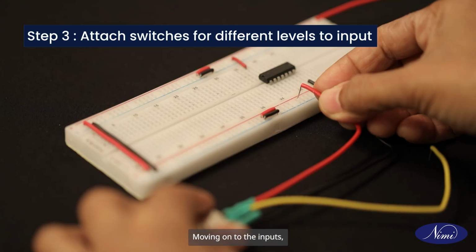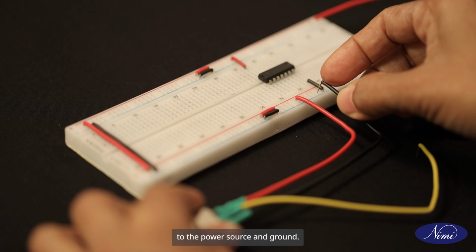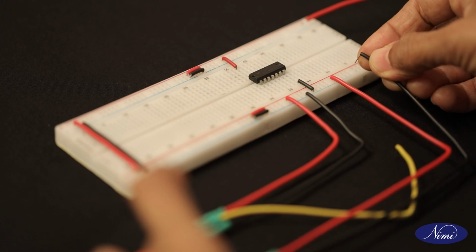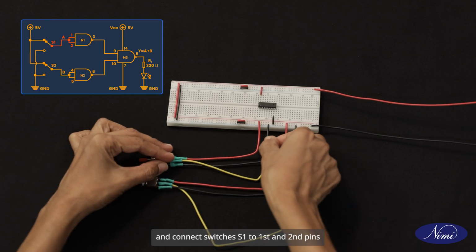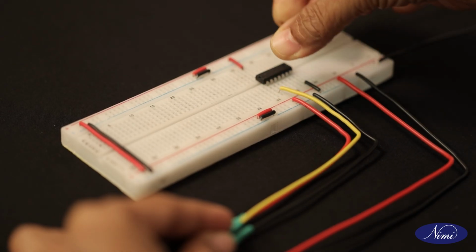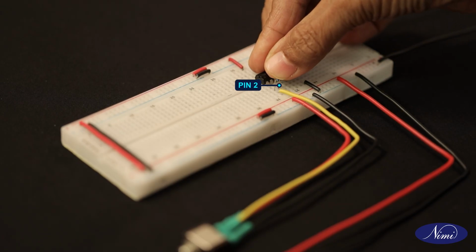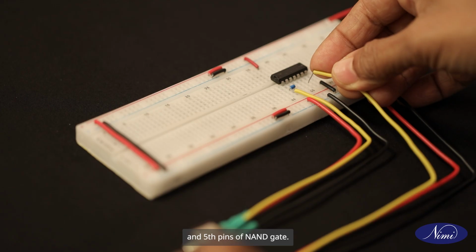Moving on to the inputs, connect both terminals of the toggle switches to the power source and ground. And connect switches S1 to the first and second pins and S2 to the fourth and fifth pins of the NAND gate.